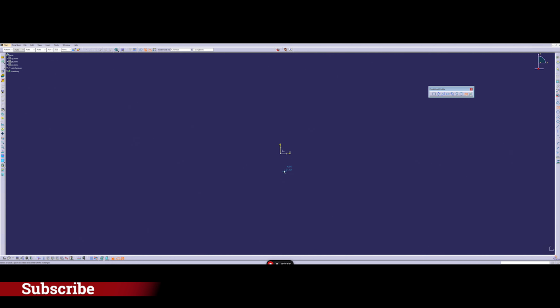With this command, we can start designing our part starting from the origin of the axis. By clicking there, you see that I can change the dimensions very, very easily. And apart from that, everything is constrained according to the center of the part. So I'm going to place some dimensions, and this will become much, much easier and faster. You see how easily I changed it.